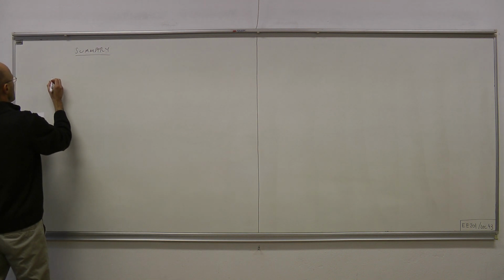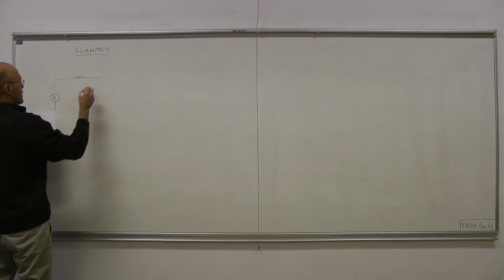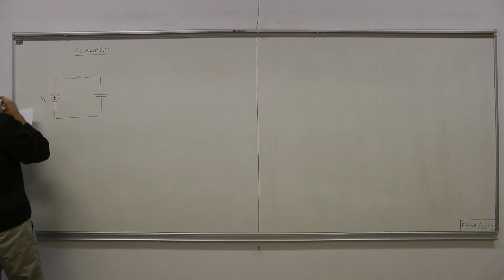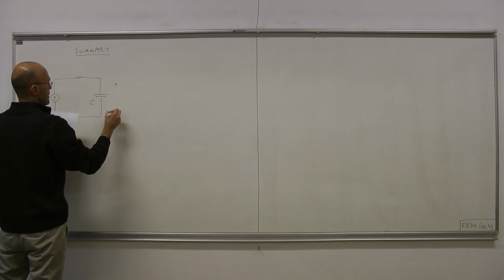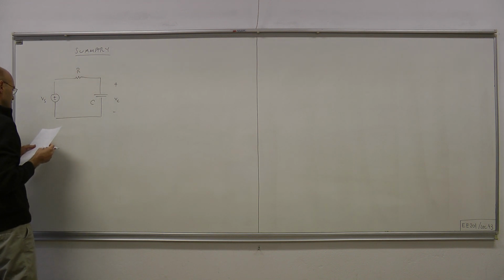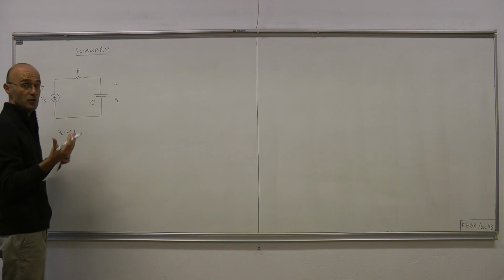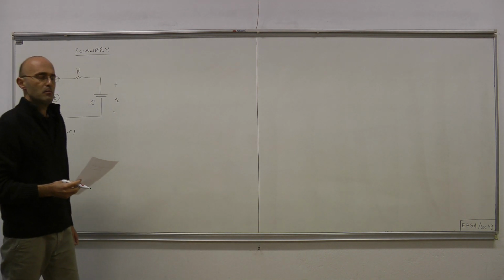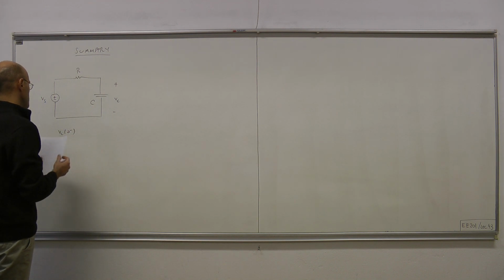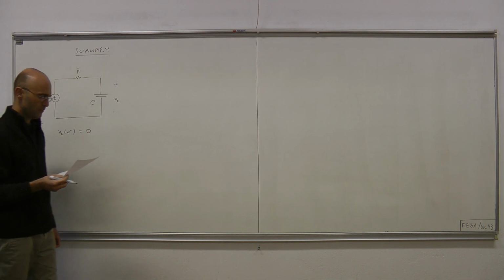Okay, we dealt with the following RC circuit. Let this be the input. This is our output, the capacitor voltage. This is the LTI resistor. We're always, by definition, when dealing with impulse response and step response, dealing with the zero state response case. Therefore, by definition, the initial condition is zero.